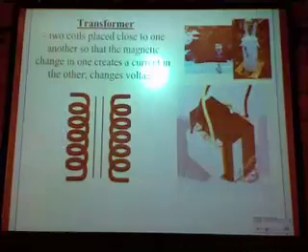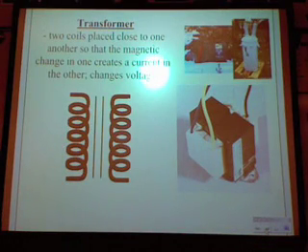So you'll see often with these transformers, whether they're big or small, that they have this piece that goes around and kind of divides it in half. And usually they're wrapped in tape, so if you take that tape off, you would see your coils of wire underneath that. Sometimes transformers have 4 wires, that's the most common. 2 for the primary, 2 for the secondary. Sometimes they have more than that. They have multiple taps. That's for other things that we won't get into, okay? But you can recognize them by that basic shape, that piece that goes around.